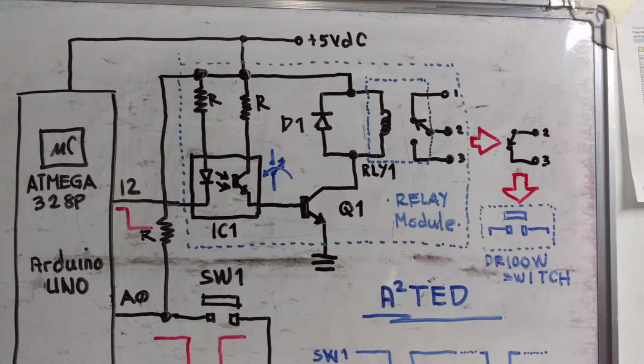During the time that the Arduino Uno sends a logic high, this logic high here, the relay will be deactivated. What will happen is that the voltage stored in the inductor will be released into the circuit. To follow the industry standard of connection, we can place D1 to make sure that every time the relay is deactivated and the voltage is released from the inductor, D1 will clamp it and kill that voltage, avoiding it spreading throughout the circuit.